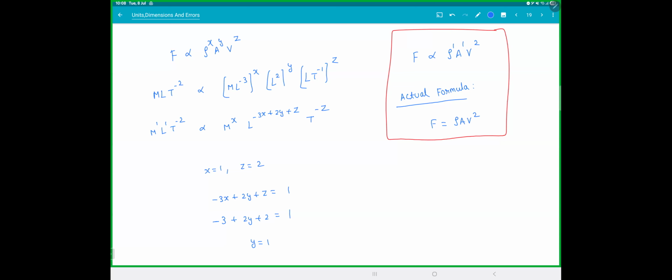Anyway, so that is a force due to a water jet, which is rho A v squared. It is actually used in construction of roads also. Let's say you want to remove the old road and build a new road. They actually use these water jets to hit the road and remove the concrete layers. It's called hydro demolition. Diamond cutting, diamond is difficult. Diamond is too hard. You use another diamond to cut it. Anyway, so this is one way of doing it.